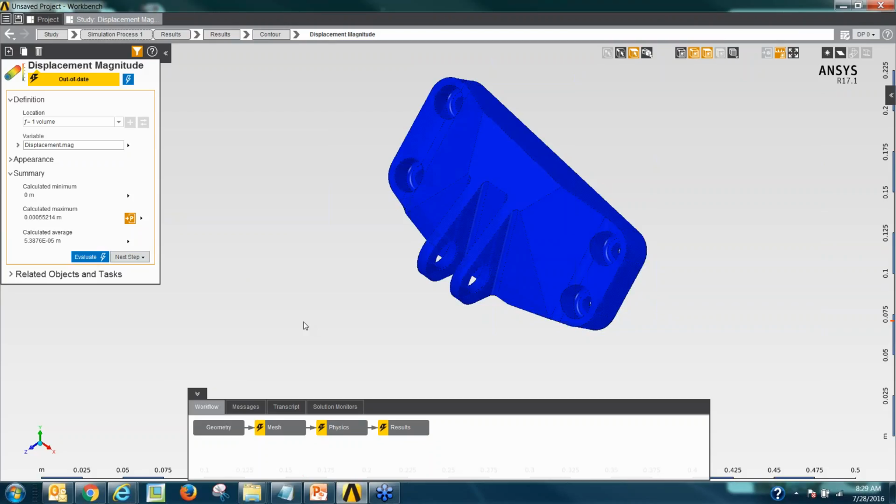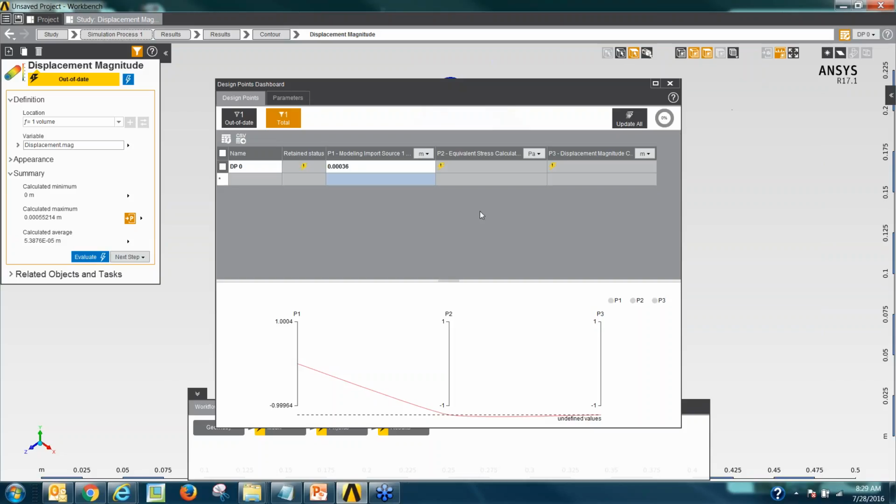So this is almost like creating design points and design outputs or analysis outputs. You're mapping them. So when I go to my design points dashboard, it allows me to see what is the dimension I selected or exposed on the CAD side or in the editing geometry environment. And I could start adding, right? So for example, I want to have slightly different values here.